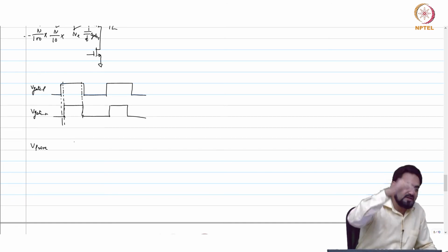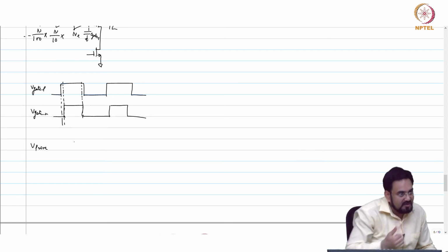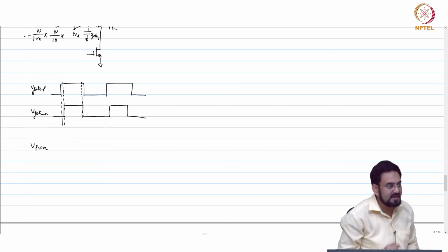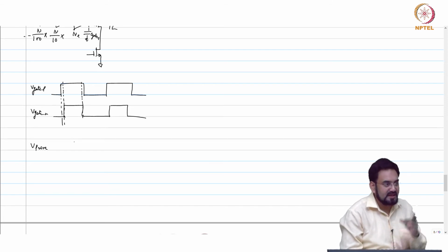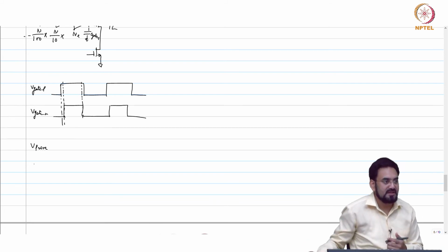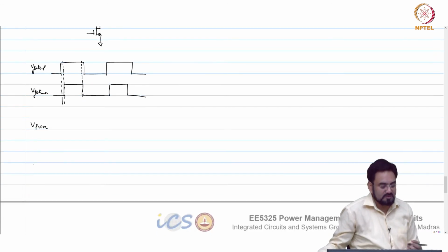Same way, if PWM is going low, at a falling edge, you want PMOS to turn off immediately, but you turn on NMOS after some delay. That is how you introduce this dead time. So we have to build a logic where at the rising and falling edges the devices turn off immediately, but turn on after some delay, which means you need some kind of feedback.